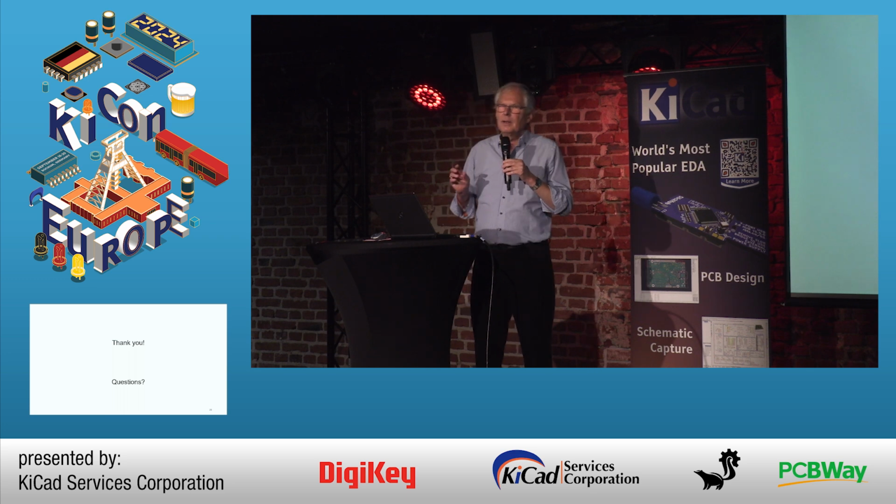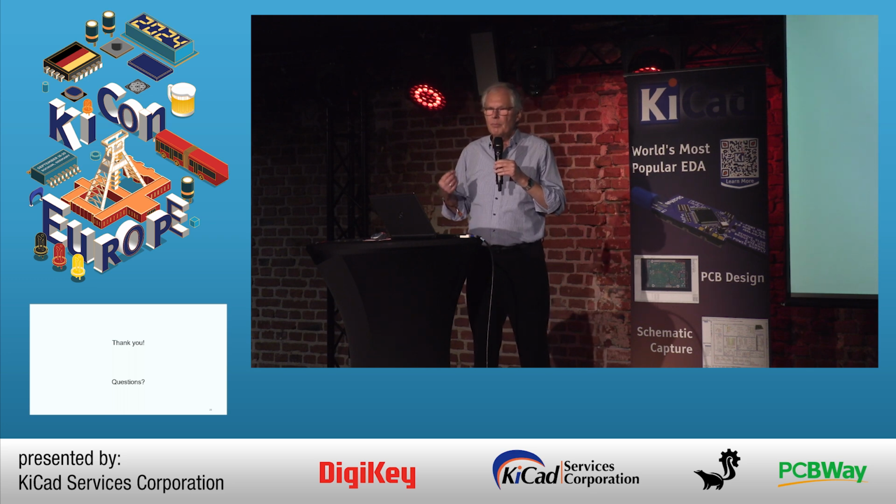Again, the simulator kernel is the same for most of the SPICEs around the world. The access to models is the other thing. We try to be compatible to models written for PSpice, for example. Most of these operational amplifier models and ICs offered by Texas Instruments have a PSpice simulation model, and we have to be compatible with that.